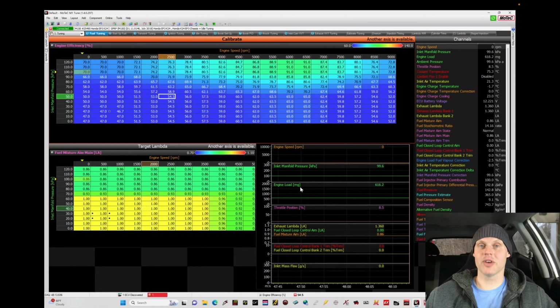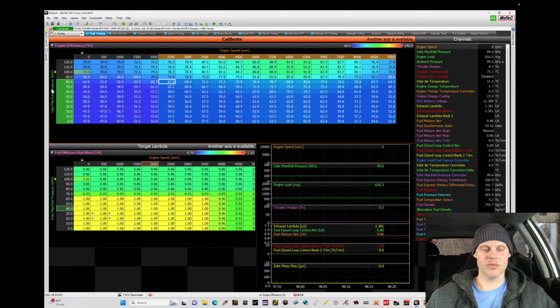Welcome back to our live training session. In this training module, we're going to be taking a look at how to dial in our part throttle cruise area of operation. So we're going to be looking at how to dial in our volumetric efficiency table values from roughly 80 kPa and below. We're also going to be taking a look at dialing fuel injection timing, so we can get that sorted out. We're going to be taking a look at setting up and tuning our estimate table. That's going to be for the map sensor failsafe or backup. We're going to be making sure we've dialed that in from 80 kPa and below as well.